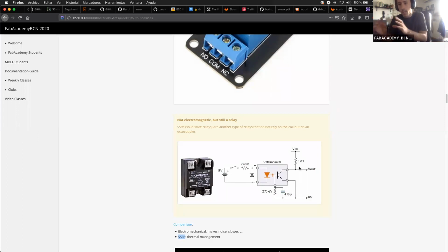But on the actuator side, it depends on the actuators that we have. For example, pumps can be at 12 volts DC and 1 amp, and that cannot be handled by the Arduino. So we need an external power supply that is able to feed enough energy into the pump, but we don't want that to be permanent. We want to control how that happens. And the way that we control that is by putting a relay, a switch, that we can control with our small electronics with 5 volts on one side, and that can manage high currents on the other.